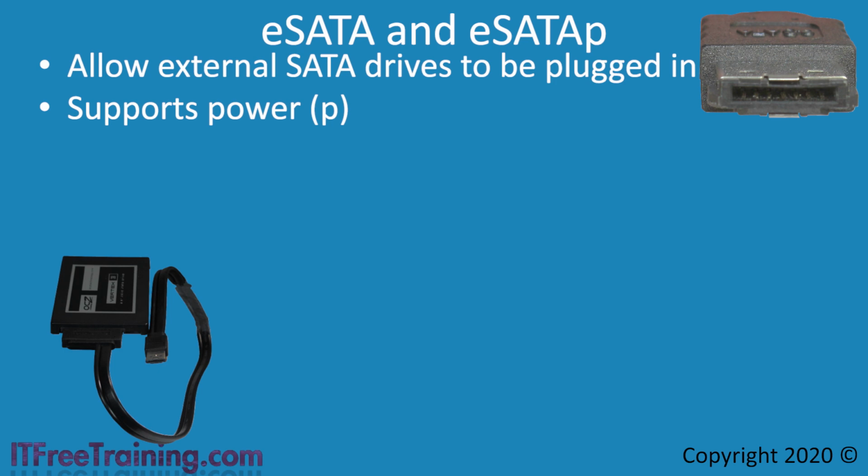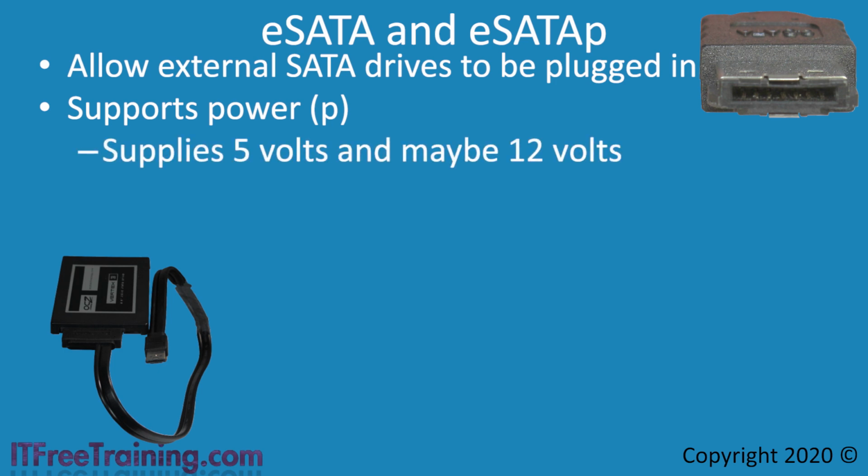The power provided by the eSATA port will be 5 volts, but may also supply 12 volts. Desktop computers will generally supply both voltages. Laptops may or may not supply both voltages. If you are plugging in a storage device that requires 12 volts, you can still use the eSATA plug. However, you will also need an external power supply.